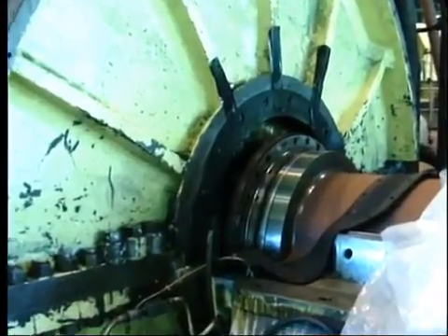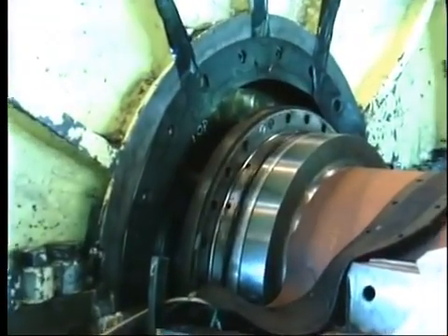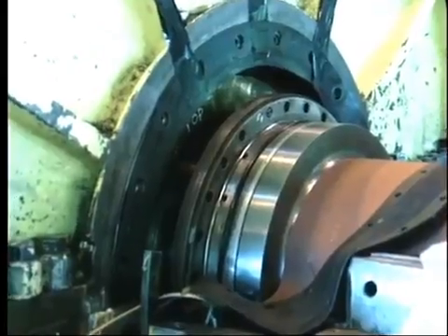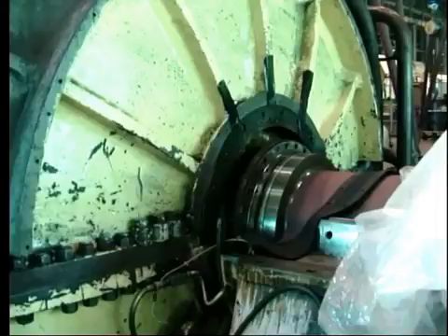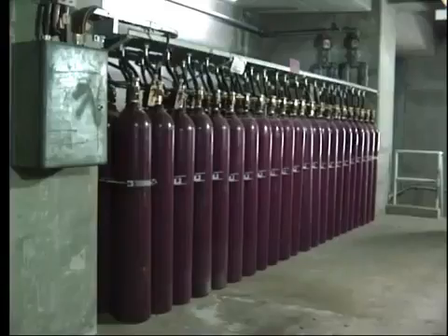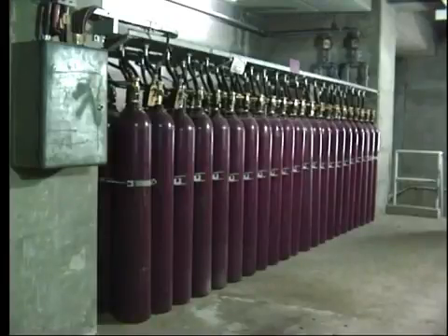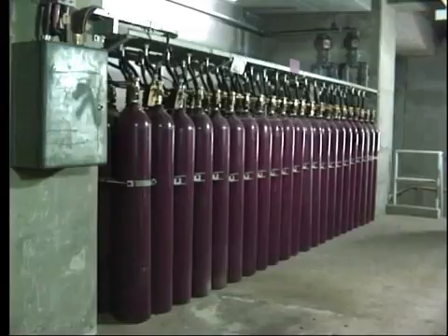But what about the mid-range? Well, this potential problem occurs when the generator is shut down for maintenance and we need to open it up for inspection. How can we discharge the hydrogen without it coming into contact with air in the explosive range? The problem is resolved by eliminating the possibility of hydrogen and air coming into contact with each other inside the generator. First, the generator is purged of hydrogen by filling it with carbon dioxide, CO2, under pressure.